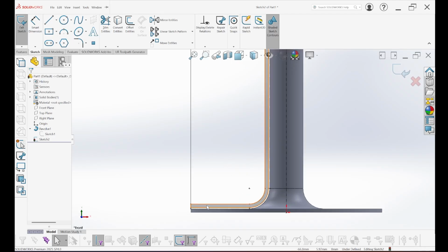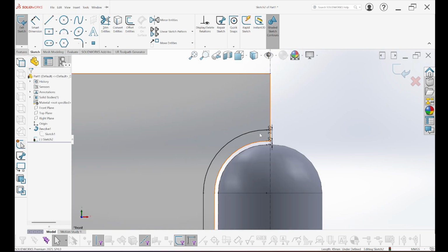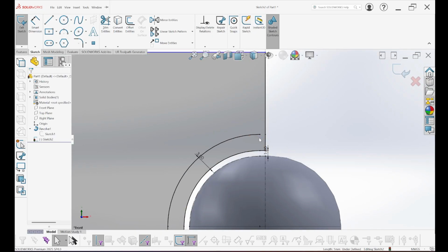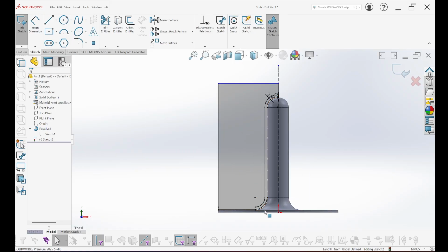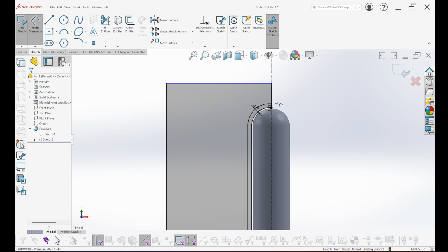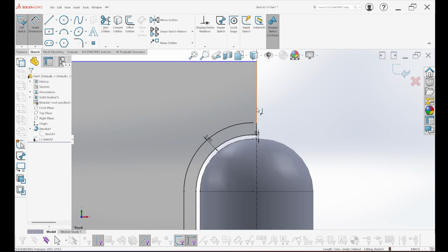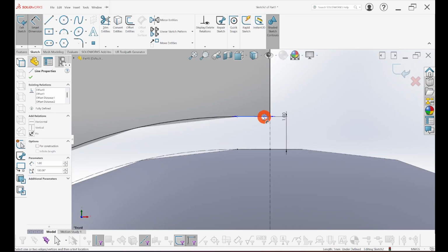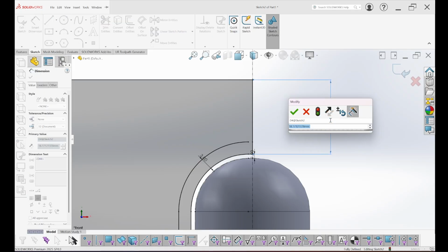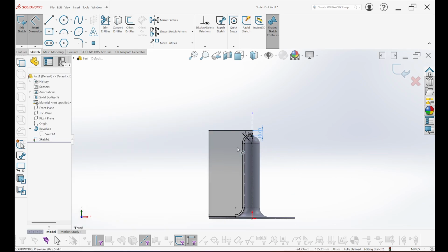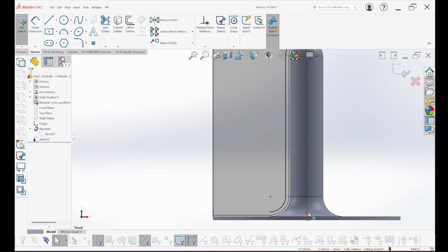Here, what I advise you to do is to click on this line that we just did, delete, and click on this line here, delete, and actually, you know what? Let's make it hollow so it's gonna use less plastic. So I'm just gonna ask what is the total height of my product. So how much do I have between that line and that line? So that's how much I'm adding on the top of the box, say 1 centimeter. And the rest of the sizes is getting from the sketch.